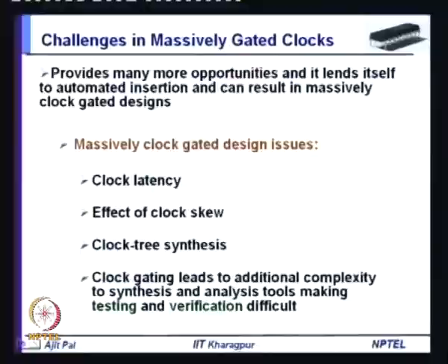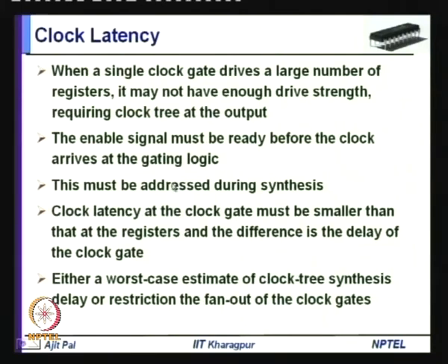As you add clock gating hardware, delay of the circuit increases and static timing analysis becomes more complex and difficult. Not only static timing analysis, but you have to keep provision for testing; built in self test based circuit has to be incorporated, and that becomes more complex and verification becomes more difficult. These are the things which will be faced whenever you go for massively clock gated design, but in spite of these problems and challenges, they can be used, and let us discuss some of the challenges.